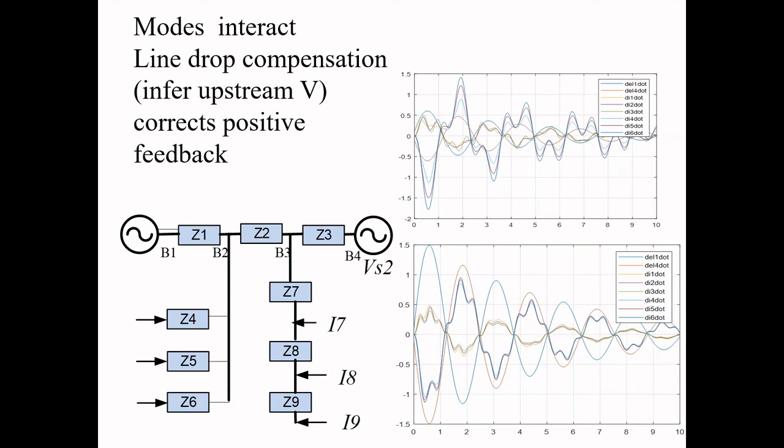So I'm not claiming that there are zero issues for the Kalman filters themselves, but in this situation here, the Kalman filter for each of these operating, ignoring some substantial variations from other inverters, is still working quite robustly, and we can get a much more stable operation than if we were just working to the terminals.